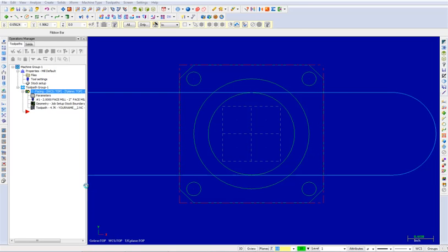In this video, I will show you how to circle mill the inside hole. Circle Mill Toolpath removes circular pockets based on a single point. You can select either point entities, center points of the arcs. Mastercam will then pocket out a circular area of the diameter and to the depth that you specify. To remove the toolpath display from your screen, press Alt-T.